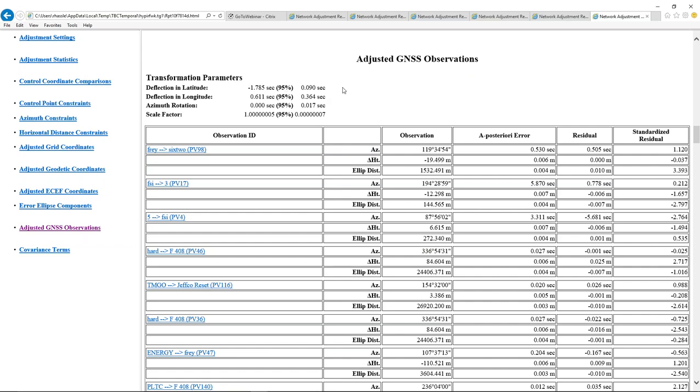So I have some tilts. You need to look at those and say, well, over the size of this project, do those kinds of tilts make sense? If you fixed one bad vertical right now, it would probably represent quite a large tilt in the network. I mean, if it was a really bad vertical value, you would actually see tilts that don't make sense over the size of the project. If I'm seeing 30 seconds or 15 seconds even of tilt, that's an awful lot of tilt.